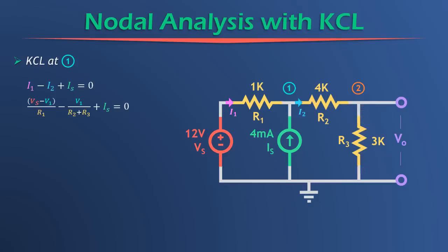And now, what is the voltage across R2 plus R3? Well, it's the voltage at node 1 up here, V1. So it's V1 with reference to ground that is the voltage across R2 plus R3. So that's why we have that term there. And IS is simply tacked on the end like we did before, because we have no other way of defining it.